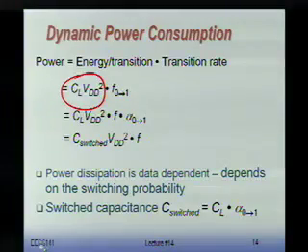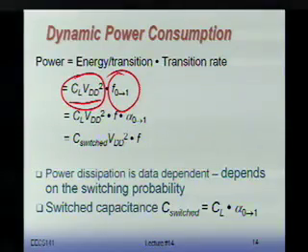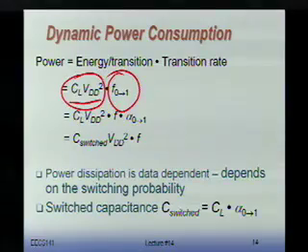So the power dissipation is going to be CL VDD squared multiplied by the frequency of the 0 to 1 transitions. Okay? Now, what's that? This is one of the hardest problems. In terms of performance, if we want to compute performance, we know what the critical path is, we simulate the critical path, we're done. Right? That makes analysis for performance quite easy. Well, quite easy is not the right word. It might take some effort, but it's quite easy.